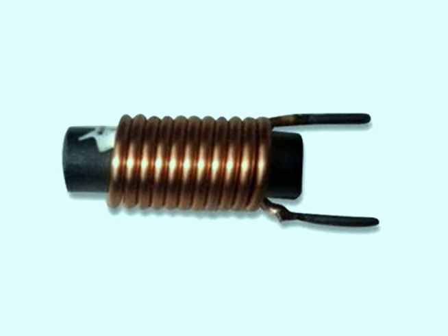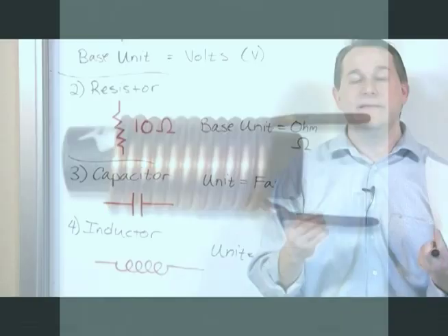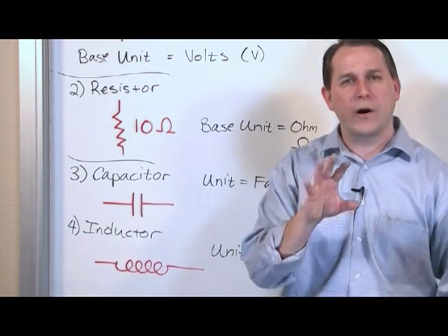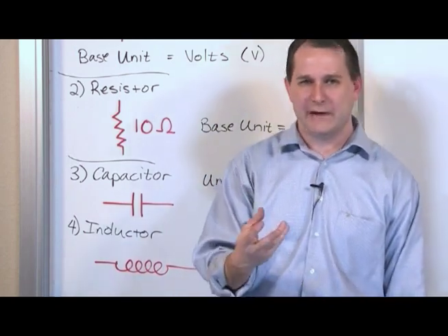If you put metal in there, of course you have an insulated wire, you don't want it to touch the metal, but it's going to concentrate the magnetic field a little bit more, and you're going to change the inductance a little bit, and so on. So there's different ways to construct them, but ultimately you're just trying to make that inductance a specific value for your application.